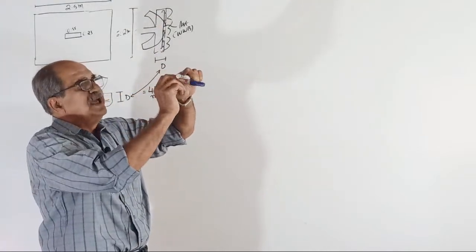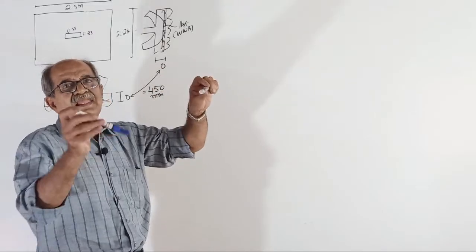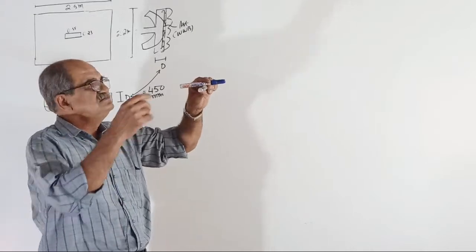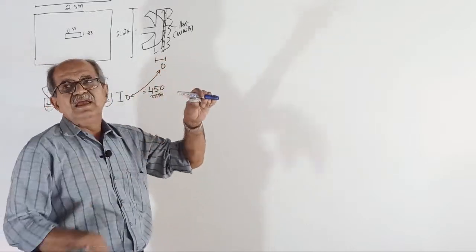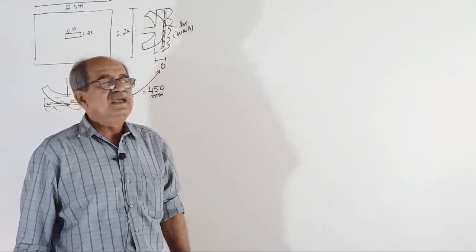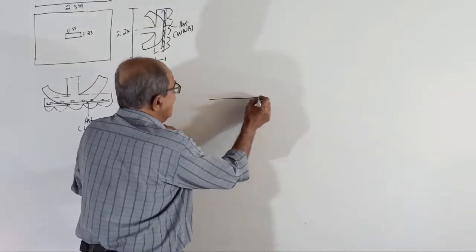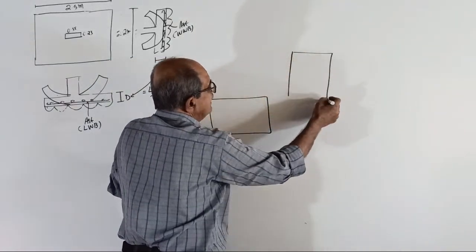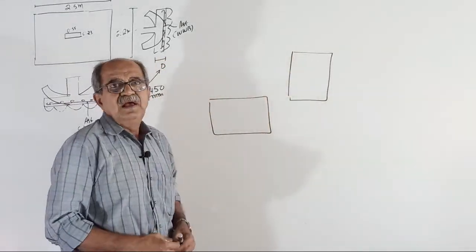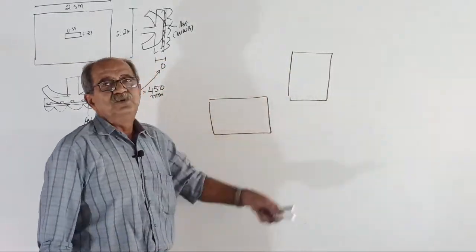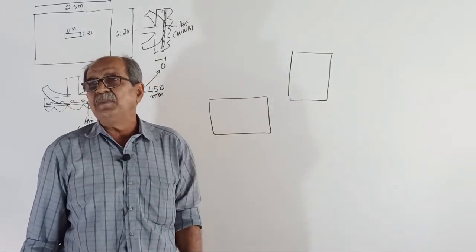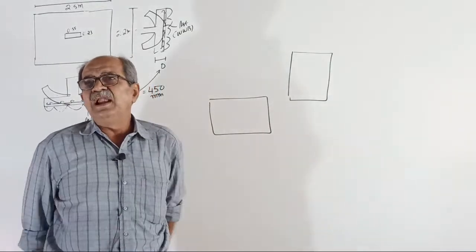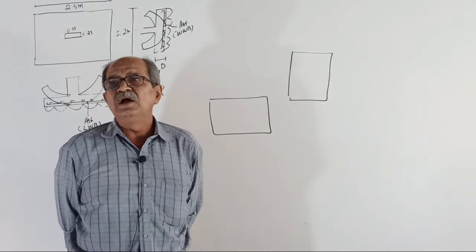Or suppose you place the widthwise bending steel here, and lengthwise above that, for some reason, then in the construction this will have lesser d, that one more d. You cannot tell how they place it. See, sometimes we are writing the footing like this. For some columns, the footing can come this way. Therefore, along the longer side or shorter side, you cannot tell how practically they provide the bars. Therefore, suppose there is a mistake. What will happen? Where d is lesser, if you take d more, it becomes weaker.